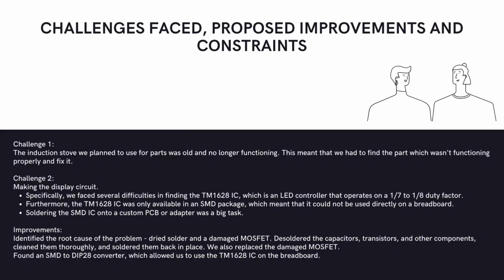The main challenge that we faced was that the induction stove that was given to us wasn't functioning, so it was challenging to decide which parts were working and which weren't. Also, making the display circuit was very challenging, because specifically we faced several difficulties in finding the TM1628 IC, which is an LED controller that operates on a 1/7 to 1/8 duty factor.